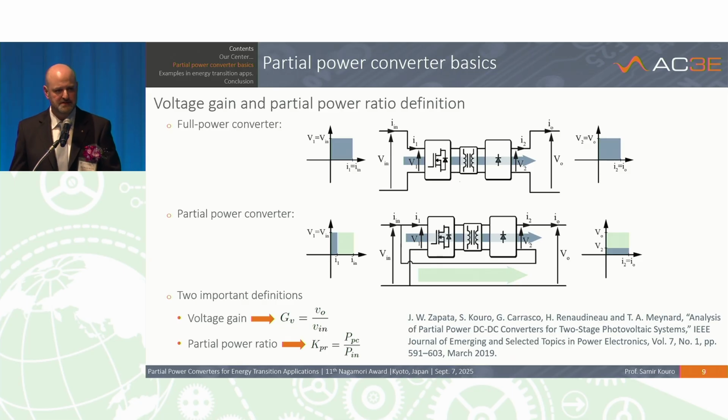So to achieve this, we used high-frequency isolation transformers to produce something that we call an autotransformer, but with electronics, in which we can connect the input to the output to provide this bypass flow, shown here in green, and only processing the blue part that you see over here. Thus, we only have to process a very small portion of the power.